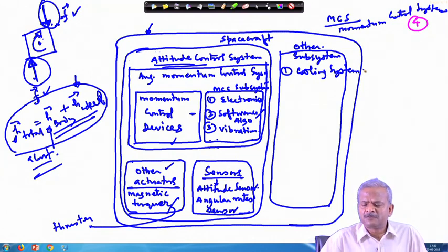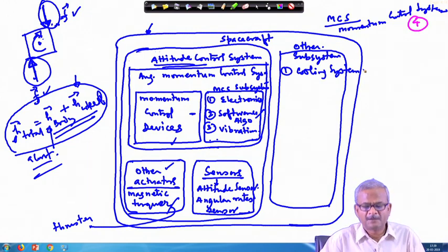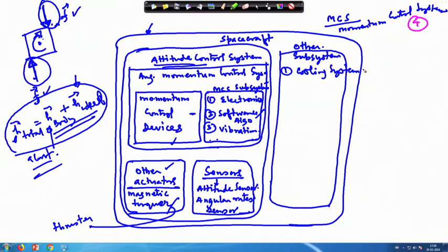So, for half a minute it will be facing the sun on almost one side. So, if we look at it this way, the satellite undergoes cooling of the structure and heating of the structure. This generates what are called thermal stresses. Okay. So, you need proper management for that, otherwise many systems can fail. In the case of the Chandrayaan, the same thing happened.